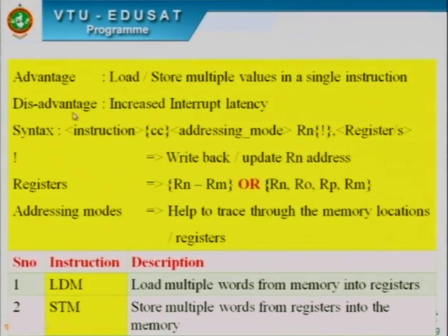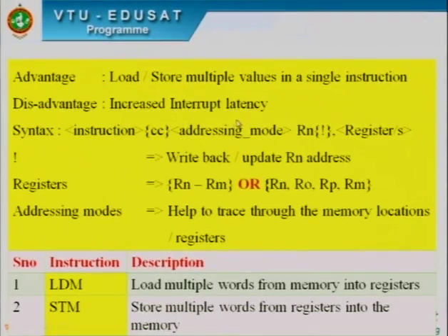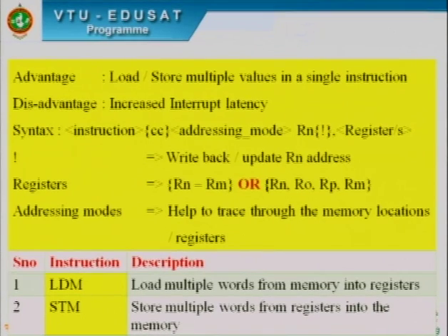Let's start with this. The advantage of this instruction is that we can load or store multiple values in a single instruction. But there is one disadvantage with this instruction. The disadvantage is that it increases the interrupt latency. Latency is the time duration between the occurrence of the interrupt and the beginning of the ISR, interrupt service routine, execution.